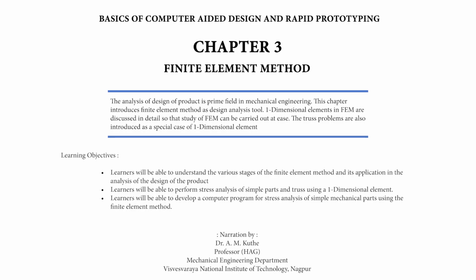The values of the shape functions at any point can be found out using the concept of area coordinate. The area coordinate at any point P over the element can be found out by joining point P to the nodal points. The triangular element is divided into 3 subtriangles. The areas of the 3 triangles are indicated as shown in figure 3.20. The shape functions of the point P can be defined as N1 equals A1 upon A, N2 equals A2 upon A, and N3 equals A3 upon A, where A1 plus A2 plus A3 equals A.